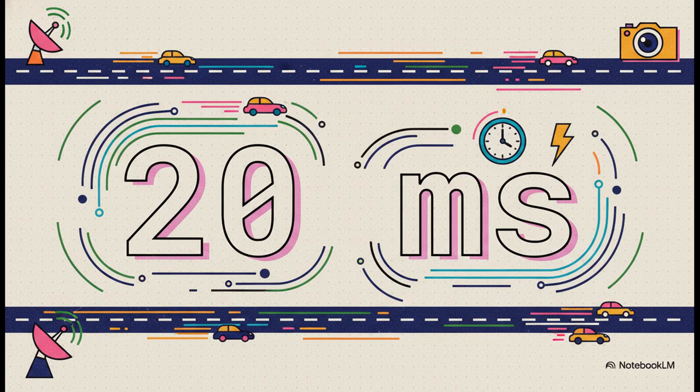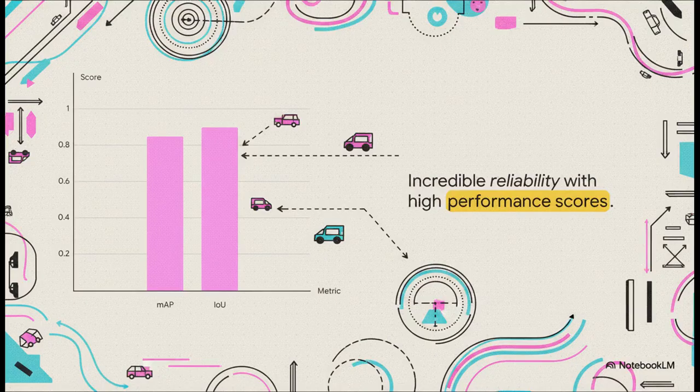By hitting 20 milliseconds, this YOLOv4 and Hough combo easily clears that hurdle, leaving plenty of crucial computational overhead for trajectory planning. And the best part? It doesn't sacrifice accuracy to get that speed. The vehicle detection hits an 85% mean average precision score. Meanwhile, the lane detection hits a really impressive 90% intersection over union score. It's an incredibly fast, highly precise pipeline.